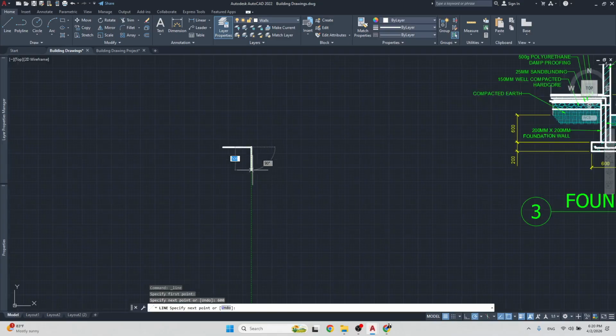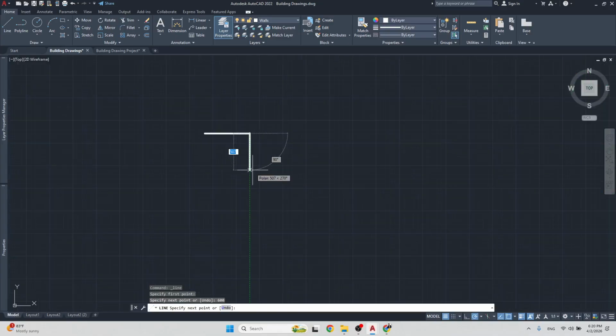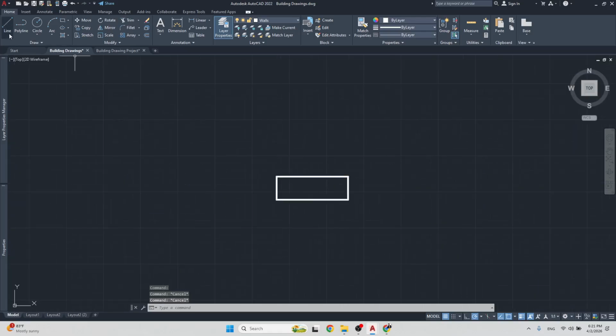Well, we know it's 2 feet wide because we're going to be using 8-inch block, which is 200 millimeters. So the footing is roughly 3 times the width of the foundation wall block, right? So foundation wall is 200 millimeters, so 3 times 200 is 600. So that's the width of the footing. So we want to put that foundation wall directly in the center. So I'm going to just offset 200 from either side, from that side and that side.